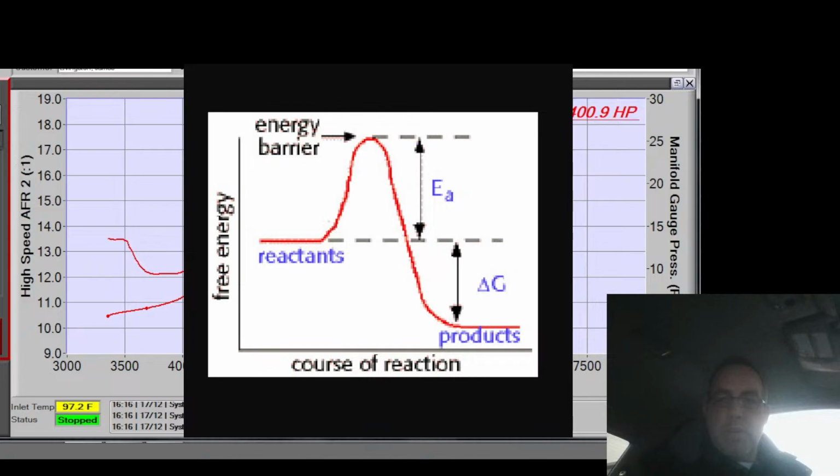This guy? Identical plug to the one I'm looking at with a slanted ground electrode. Electrode shape is mostly or typically engine dependent as to what it's going to want, and to which direction you're trying to push the flame kernel, where you're trying to start that propagation event.